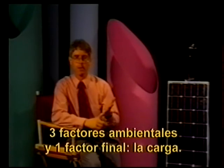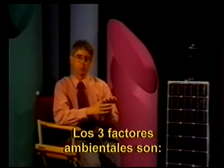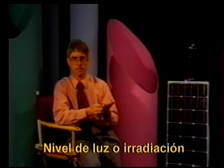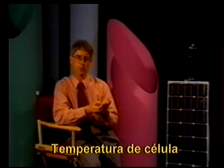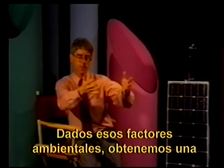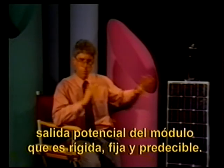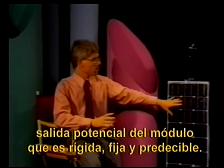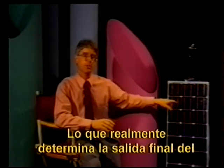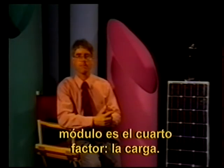It's really 3 environmental factors and a final factor, the load. The 3 environmental factors were light level, or irradiance, cell temperature, and spectrum of light. Given those environmental factors, we get a rigid, fixed, predictable potential output from the module. What actually determines the final output from the module is the 4th factor, the load.